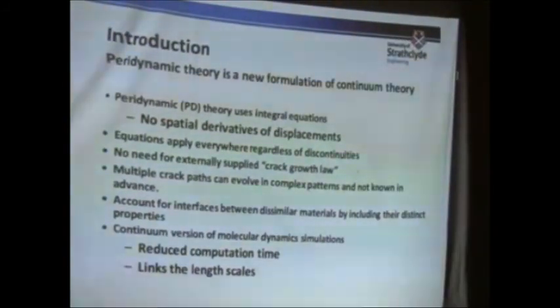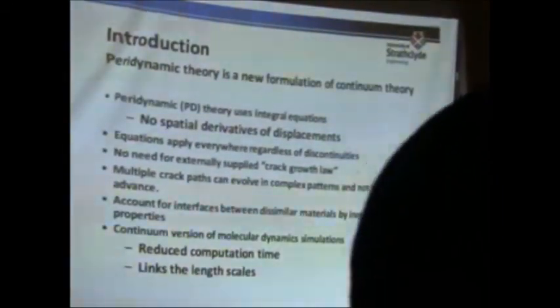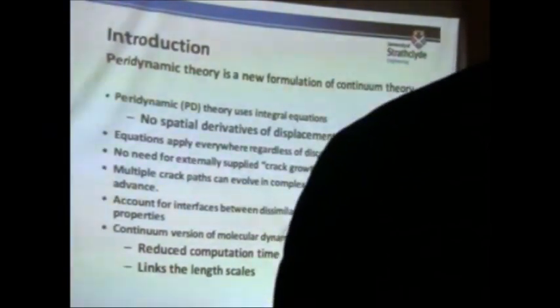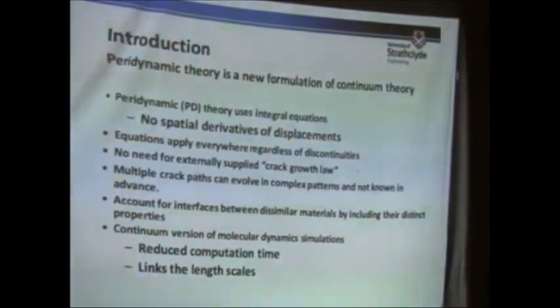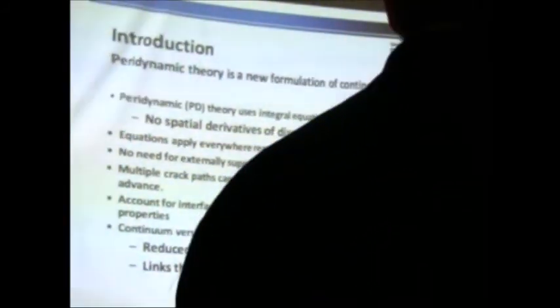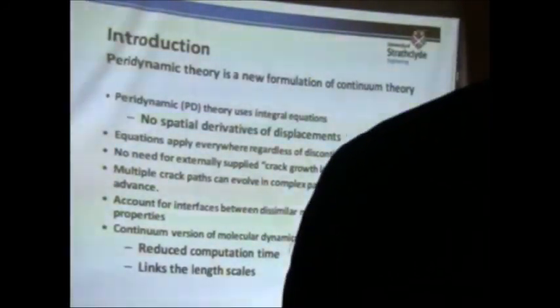So we don't need to come up with some external or extra conditions, or use additional types of formulations. Another nice thing about our formulation is that we don't need to use a crack growth law, which is not easy to come up with, especially since there is no universal crack growth law which can be applied to all materials.